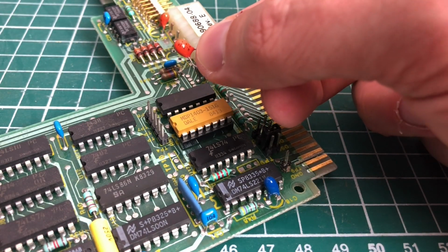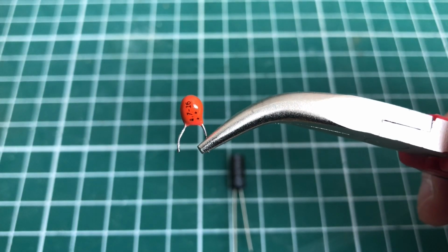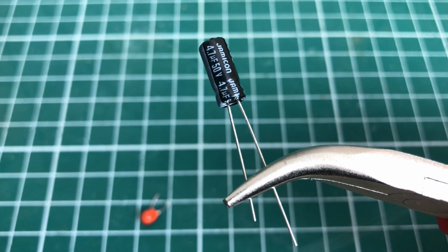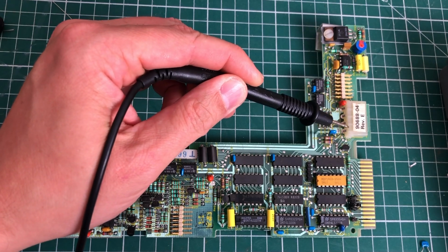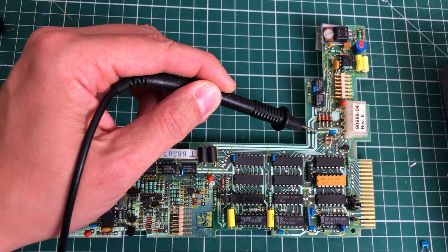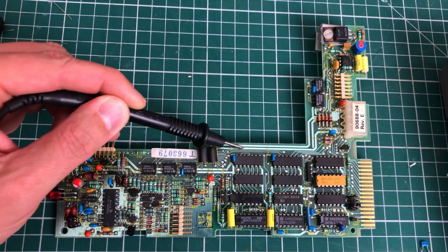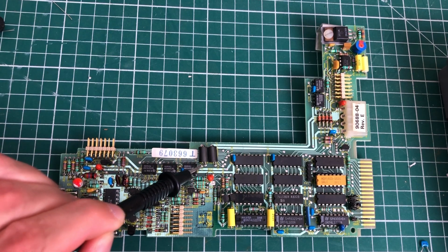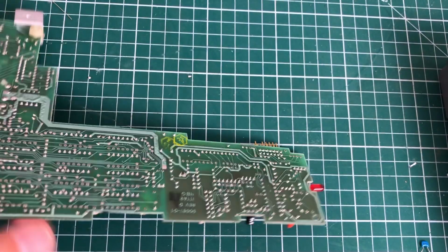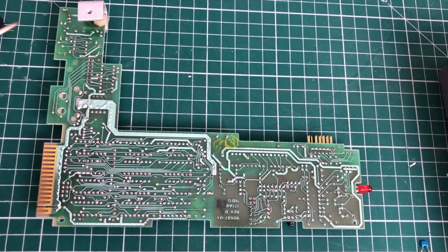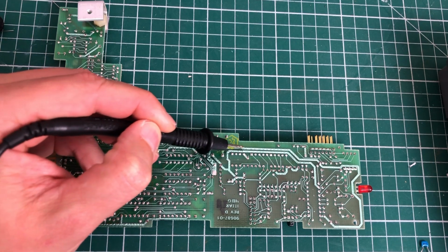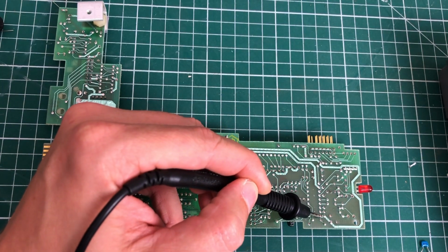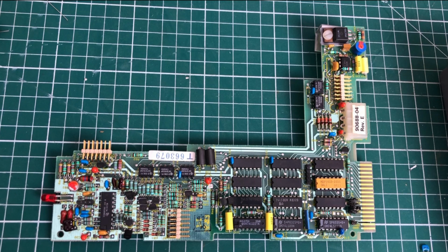Now these tantalum capacitors are very error prone. We already saw that on the main board, on the CGA card. I don't have a replacement for it, but this electrolytic capacitor should do the job also. But the short was still there even after removing the capacitor. So what you need to know is that this 12-volt line goes all the way through this line filter here and then continues on the bottom of the board. And there's an entire 12-volt rail here also. So following the path here, there are two additional capacitors on this 12-volt line that could also be short circuit.